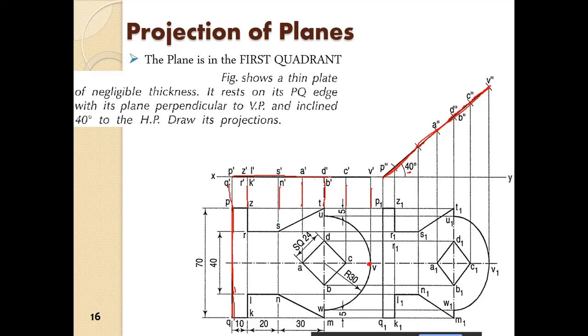front view of the initial step. All right, once that is obtained and the dimensions of the various points are obtained, you rotate this up to the required rotation. All right, so here P Z dash, P L dash, all those points you have to mark. Then once it is done, again from those points you have to drop vertical projections down.